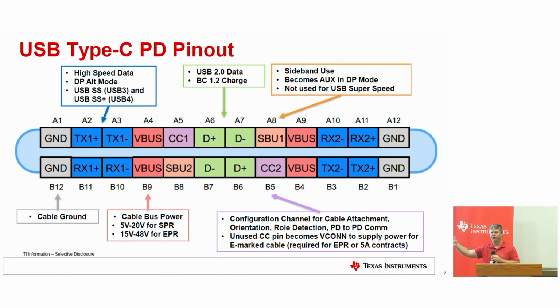At 5 volt, say it's plus or minus 10%, it can go up to 5.5, and down to minus 5%, say 4.75 volts. So you have to guarantee that you're still above 4.75 on the far end device. The cables are designed for that. If you make your own custom cable and you're going to go 20 feet long, you'd have to guarantee that you don't drop more than X in voltage across that. More of a voltage drop issue.